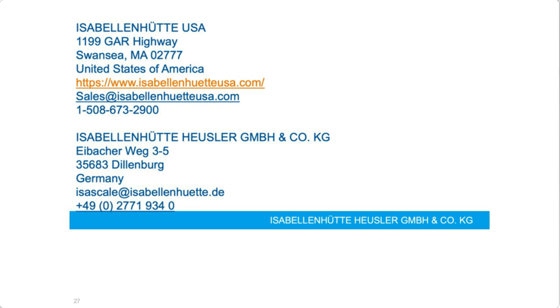And as I'm already talking about accuracy, the total sensing range of the new IVT 3.0 is 4,000 amps. And even in overcurrent range up to 4,000 amps, the total accuracy will never go below 1%, which, by the way, is also a big improvement over the predecessor product, IVTS.